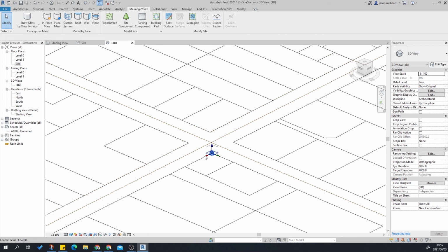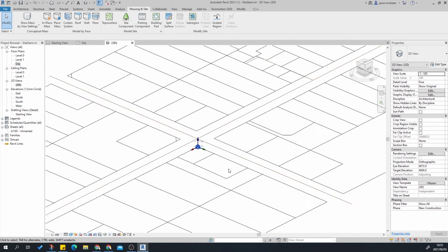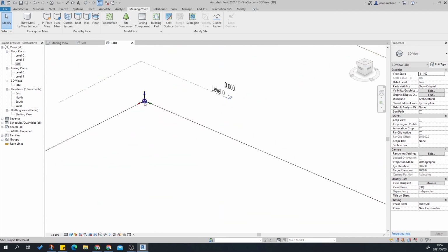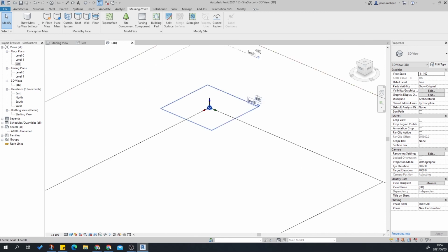Okay, so I'm going to do some basic analysis now to determine what level will need to become my datum level, meaning 0. In our floor slabs, we represent our sections and floor slabs in two methods. The first one is we use sea levels, so your levels in relation to sea level. And that's how your civil and your structural engineers work. They prefer those levels, and we tend to do the same.